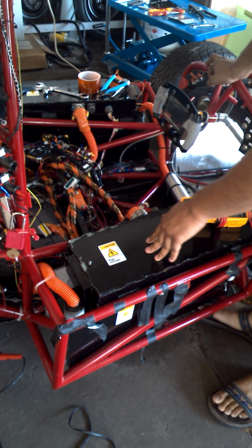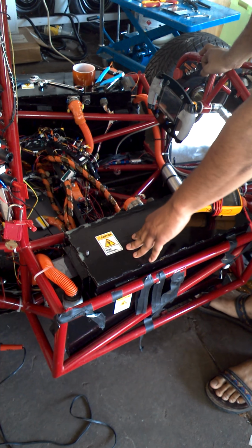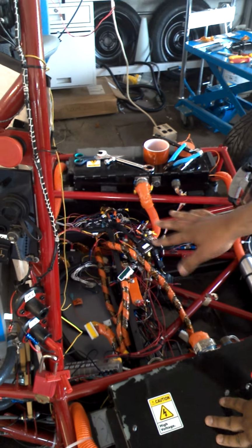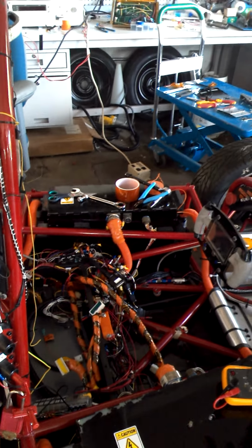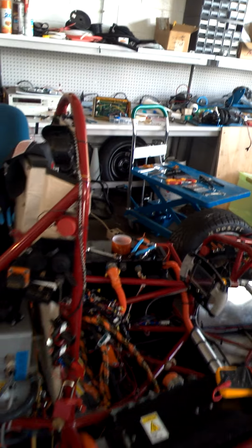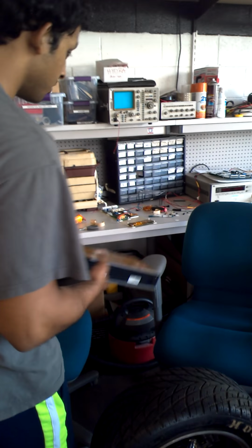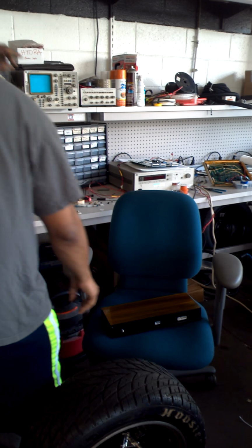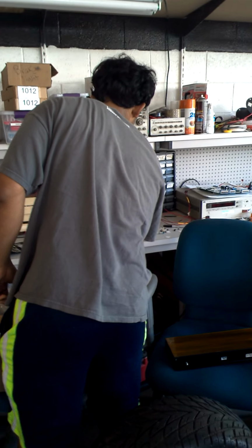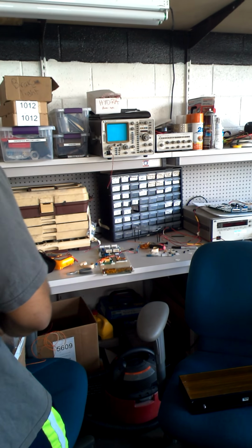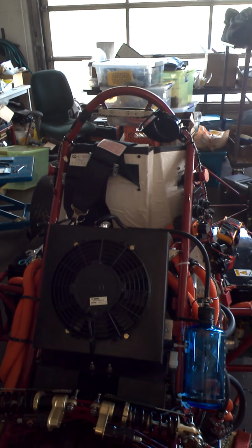These are actually high voltage. Each needs 150 volts connected in series. In the middle you have a high voltage distribution box. Right now it's kind of empty because it's missing the battery management system, which sits over here. And then more high voltage electronics here in terms of insulation monitoring, DC-DC conversion, like this active light, 2 circuits for redundancy. This is basically the entire team's work.